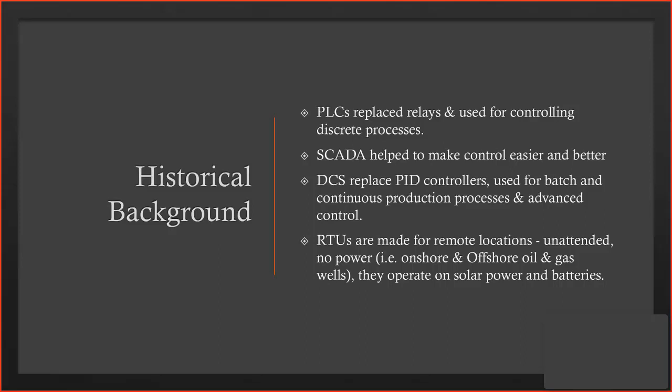Even if they don't melt down, some PLCs stop working after a higher temperature, around 50 to 60 degrees, and don't function in a proper way. So RTUs are best for those locations. That is the historical background. We started from PLCs replacing the relays, and we came towards SCADA, which I would again mention is a software layer.